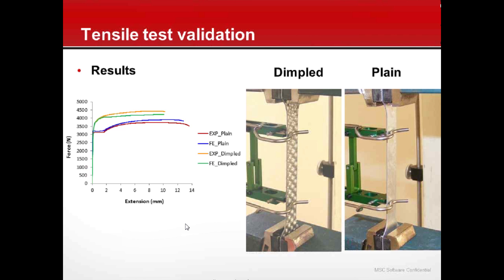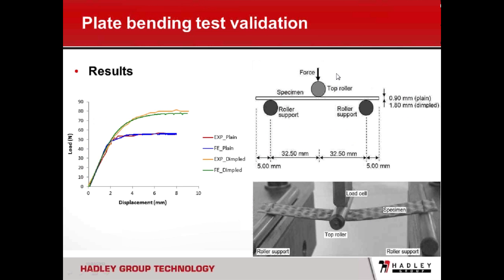In this simulation, I need to remind you that all of the stress and strain data in the dimple strip is transferred from the previous dimpling process into this tensile test. And then the other validation is that we perform bending tests on the dimple strip and the plain strip and compare with the simulation.